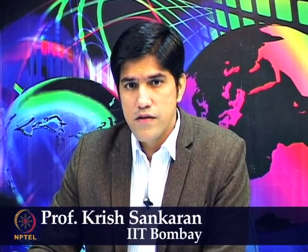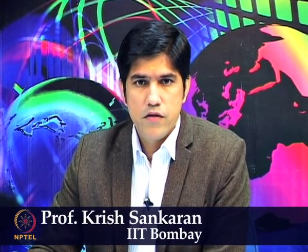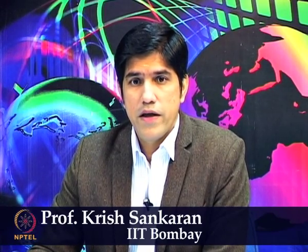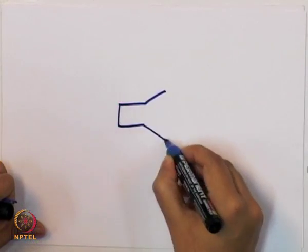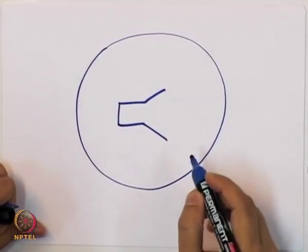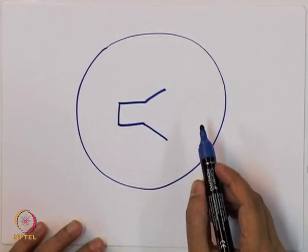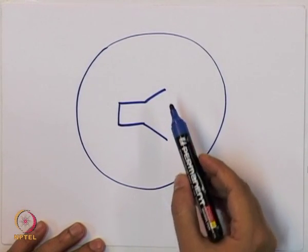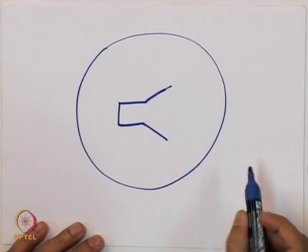We will now focus on the applications related to antennas, and we will show some examples of simple antennas, and then we will also do some more complicated antennas. In this case, what we are doing now is we will start with a simple horn antenna, which is going to be truncated in a radial manner. So the important thing is the antenna's flare direction is roughly in the x axis.